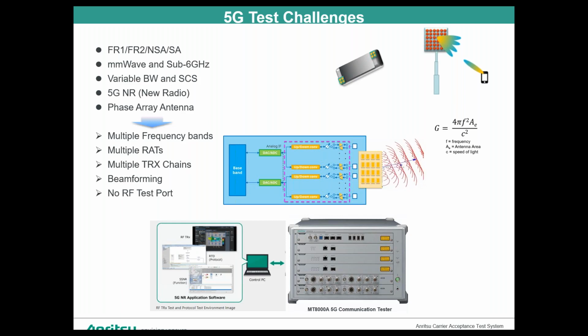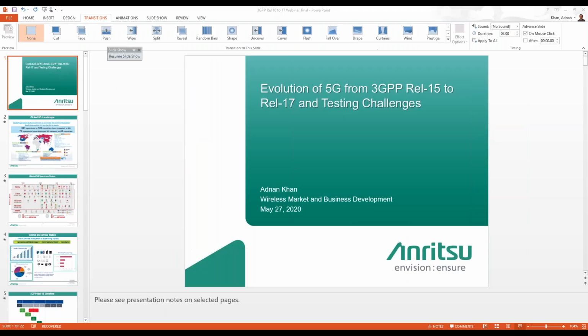when supporting FR2 and FR1, you could have a whole different implementation on your transceivers, depending on what sort of techniques you are using. Are you using hybrid beamforming? Because you have to use some sort of beamforming for millimeter wave, so you can focus your energy and kind of offset